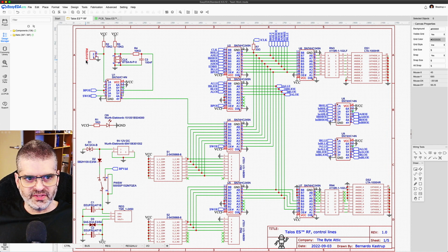You define whether the board is in system or standalone with this little pin header. If the shunt is not placed, then this is VCC or logic 1, and then it's inverted once and twice, and then you get backplane output enable being 1, which is inactive. In other words, if you don't put the shunt, you are not in system, you are standalone. And the switch output enable is just the inverted, the negated backplane output enable, and this one will be 0, or active, when we are in standalone mode. That's all there is to it.